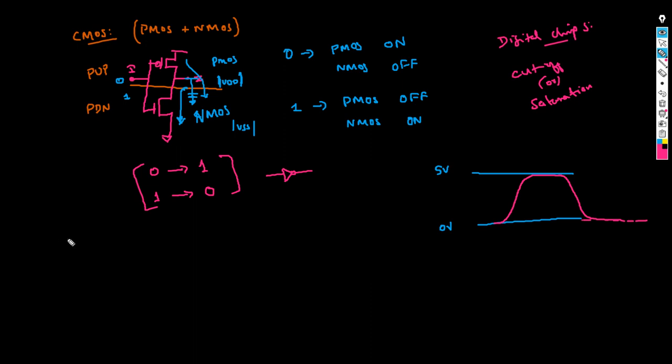Let's do a quick class work. What will happen if you interchange this PMOS and NMOS? So NMOS is on the top and PMOS at the bottom. What will happen? Sir, a buffer is created, sir. Okay, so the functionality you're saying is a buffer. Any other drawback? I mean, weak load, sir. Weak load with buffer.